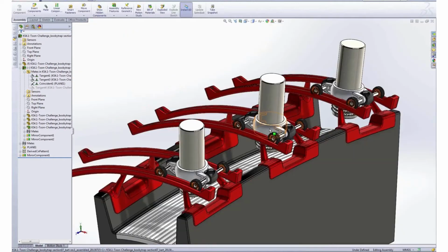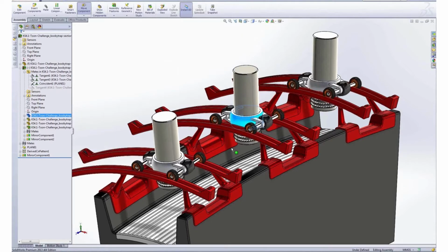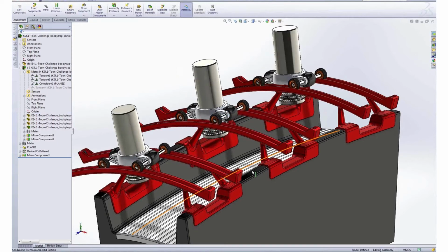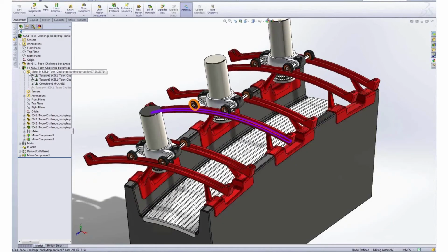So in KeyShot, if I want to emulate this movement, I will have to make sure I can pick a correct pivot point, or that I put my origin in my CAD data at the pivot point, or that my pivot point coincides with the origin. So how this looks in CAD.